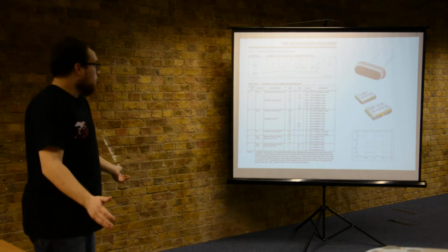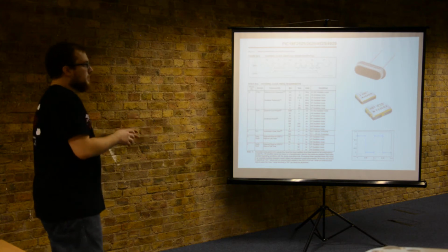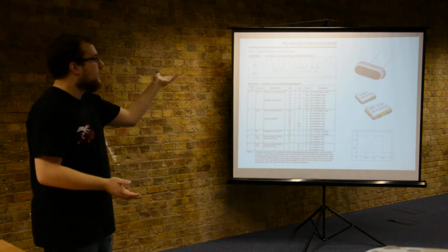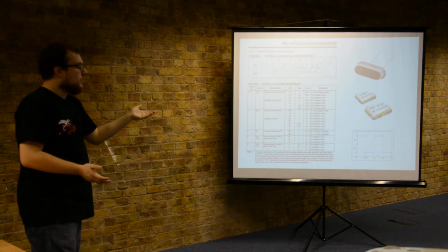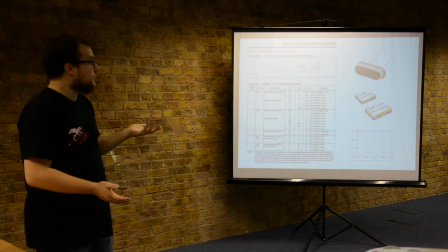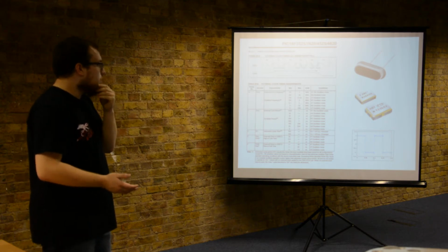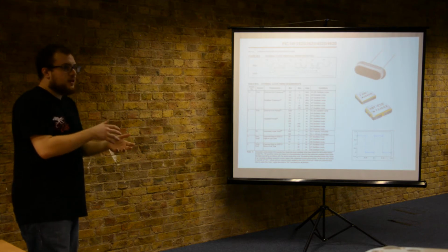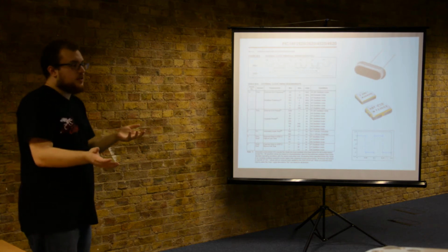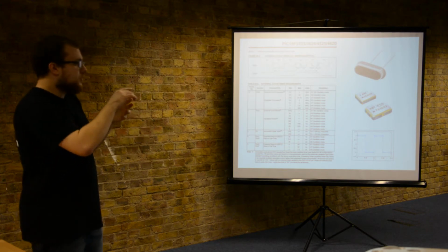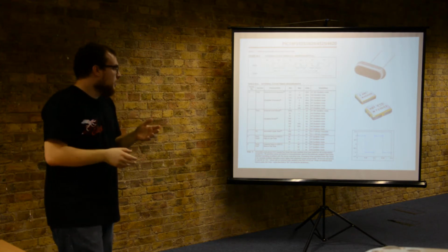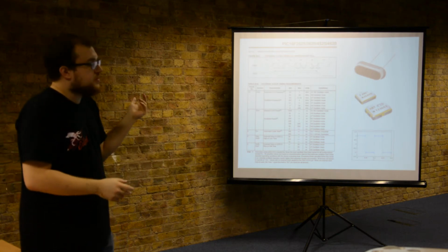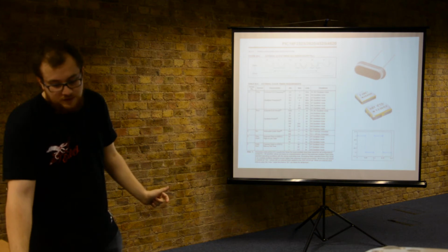And usually overclocking, I'm now talking about little embedded boards that you can overclock, can simply happen by replacing either the crystal or the oscillator, or by hooking it up to a clock source of some sort. Modern motherboards on computer systems usually allow you to programmatically tweak this. So you can say in your BIOS, I'm going to increase the clock frequency by this much. But if you're working with a small system, you should be able to just replace the crystal and then have it running at the fastest speed.